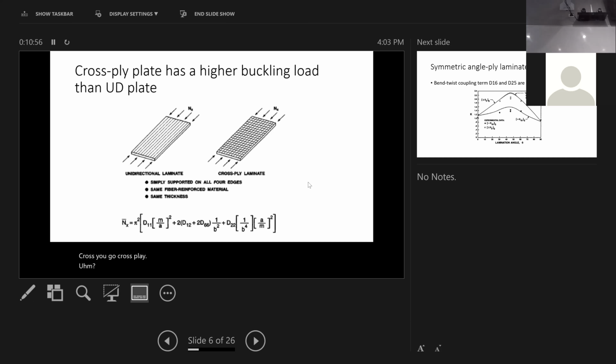Now, obviously, in the case to the left, with all the fibers along the same direction, you would have the largest compressive stiffness. It is the stiffest of them all, because the cross ply, remember, is controlled by the matrix. The cross ply doesn't contribute to the stiffness.